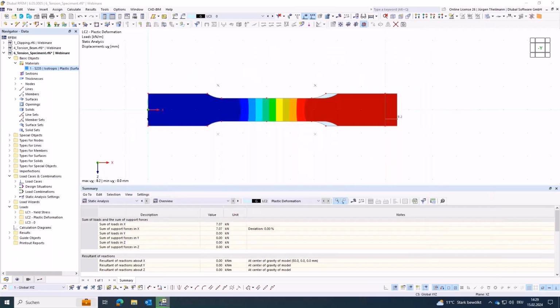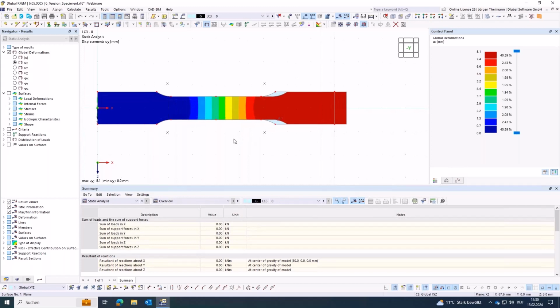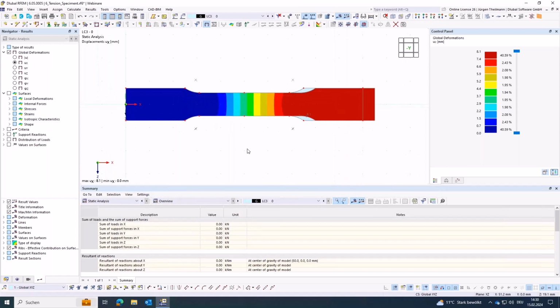then you can think of it. You're starting from that load case beyond the yield stress limit, where you have this 8.2 millimeters deformation, and now you take away the load, and the 0.1 millimeters of elastic deformations get back, but the plastic deformation stays in place. So that is a very good example in my eyes to explain the sense and logic behind the initial state.